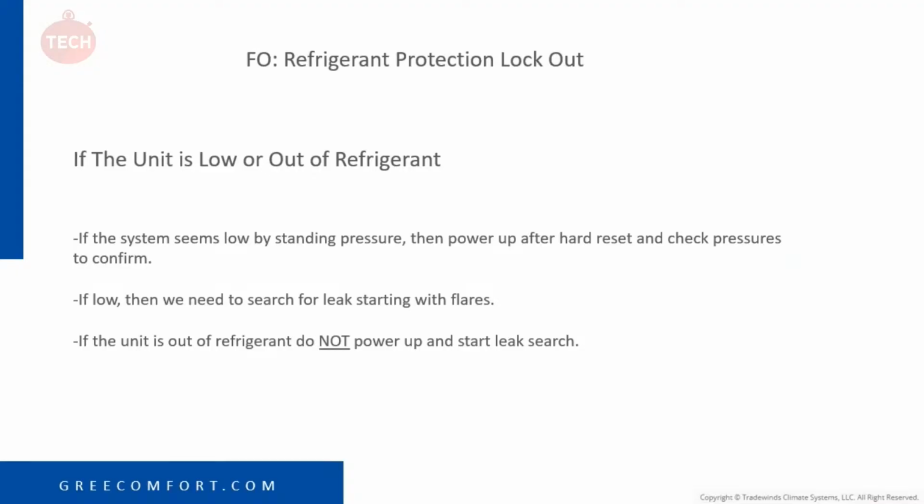Of course, it's recommended to use a torque wrench when doing the installs to prevent these leaks from happening. Again, most contractors that call in that have leaks are not using those. So again, use a flare gauge to make the proper flare. Use a torque wrench to make sure that it's torqued properly.